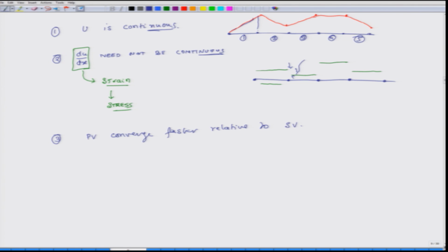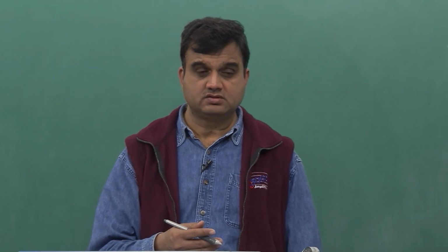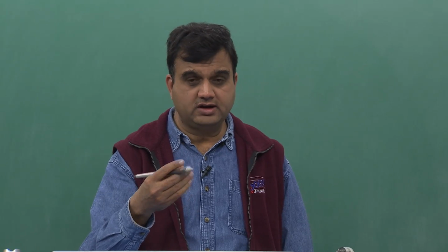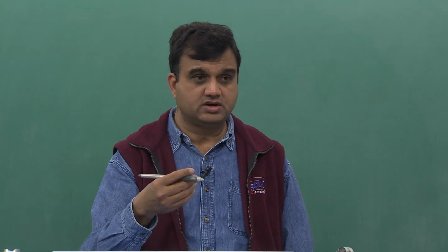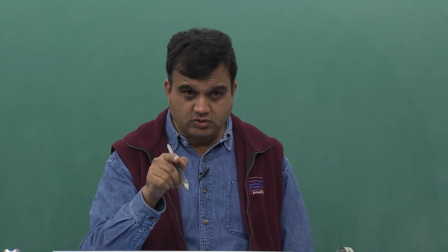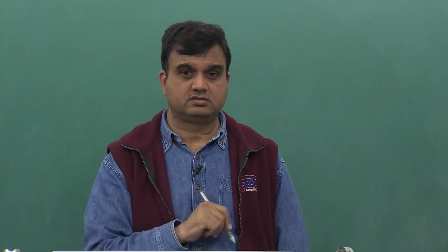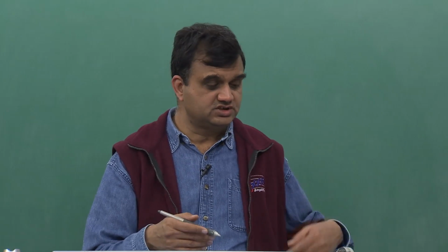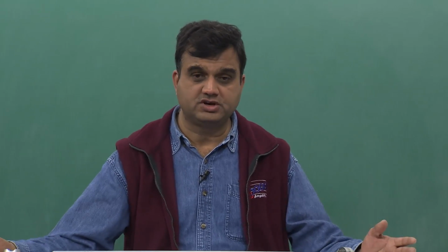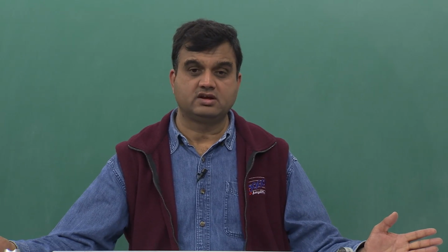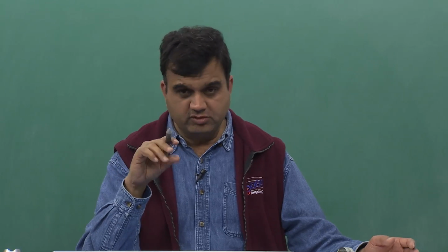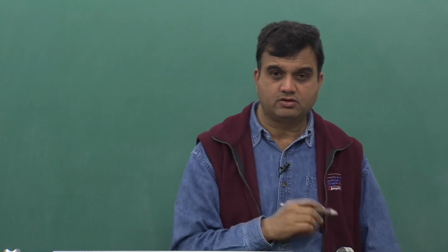These are very important things to remember, because a lot of times when we do finite element analysis, maybe our U's have converged, but if what we are really interested in is the strain or stresses, then we have to look at those quantities to see whether they have really converged or not. If we are interested in convergence of U, or for instance in a thermal problem we are interested in finding temperatures, then that is fine. But if we are interested in finding out how their gradients are changing, then we may have to do a more refined analysis with higher node numbers.